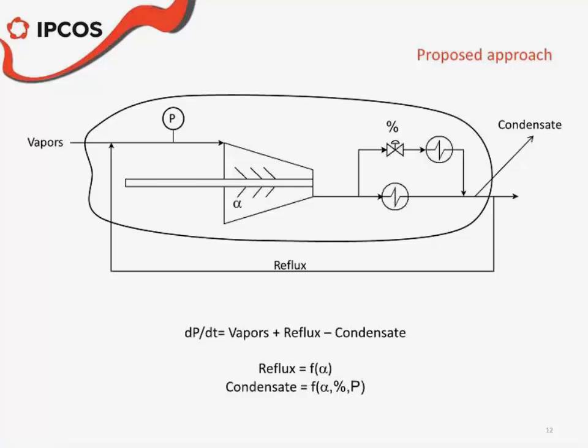That decouples the whole system and allows you to make proper regulation, because changes in this valve will not have the same effect as changing the inlet guided vanes.